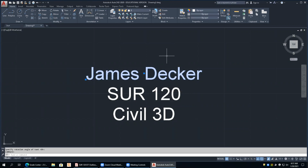Okay. So let's take a look at this text. You can go ahead and hit the escape key. That'll deselect your text. A text looks a certain way. It's being driven by the style. Does anybody recognize that font? It's very common. It's called Arial. Okay. So AutoCAD has a style in place that's defaulted to standard, and it has a font that it's using, which is Arial.